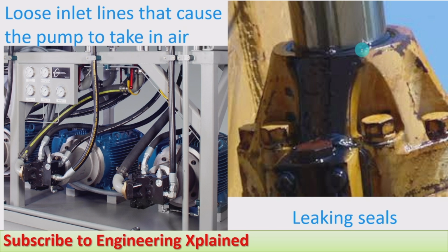And if the oil seals are worn out over a longer period of operation, then there will be leakage through it. And if it is leaking, the sufficient supply of oil will not take place, and the required power or force we are not going to get from that particular cylinder or system, and that will cause some failure.